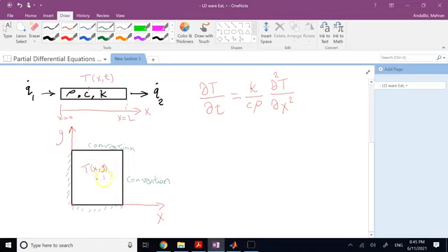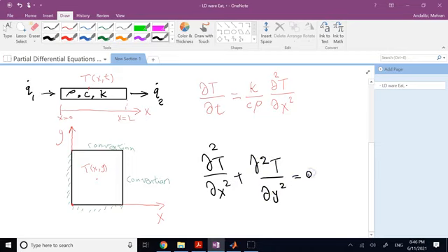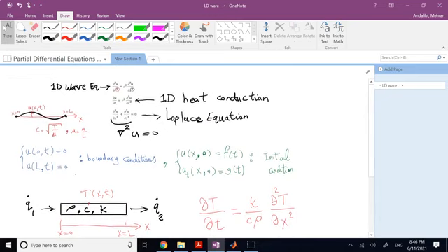We call it steady state temperature distribution in 2D, and you can show that then the distribution of T with respect to x and y follows what you had over there. It should follow this smoothness constraint or Laplacian equation. Again, as long as it is steady state. If it's not a steady state, there is a right-hand side here.